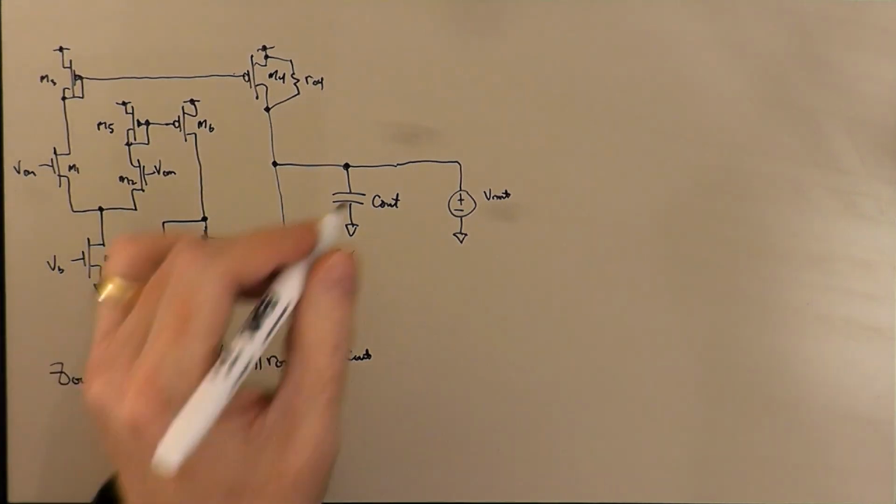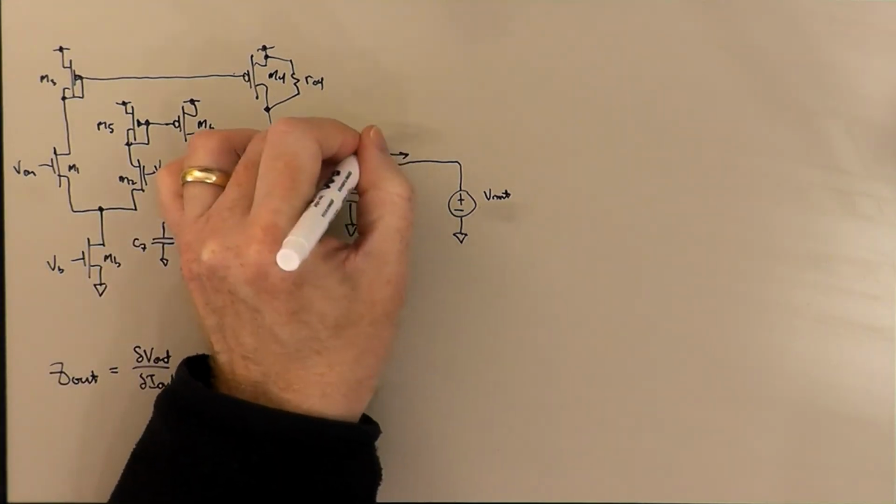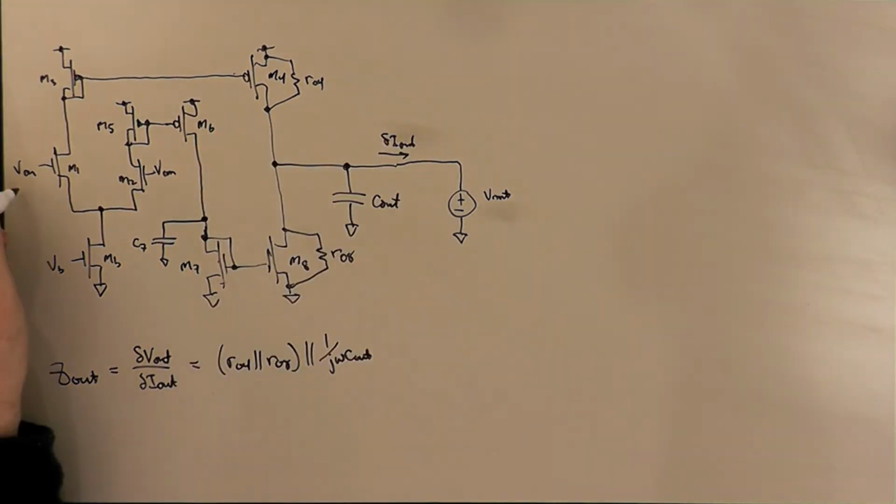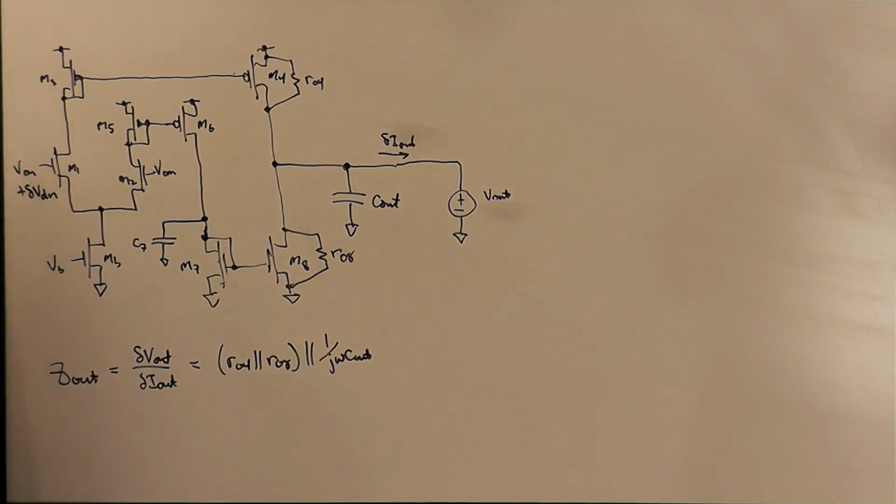The output voltage is held fixed, and we're interested in what is the delta I out that we get when we put our delta V dm into, let's say, M1. Okay? Only this time we have C7 in the mix. Well, just like before, we're going to get a delta I1 in transistor M1 because we're changing the gate voltage here.